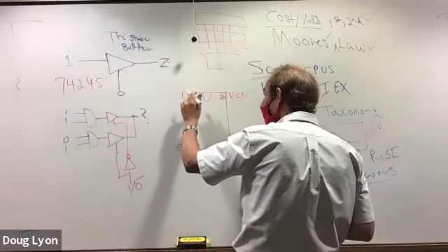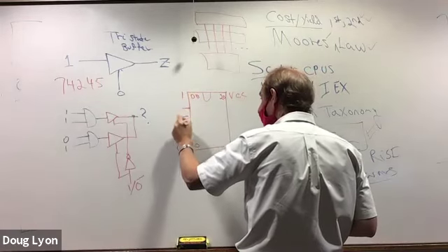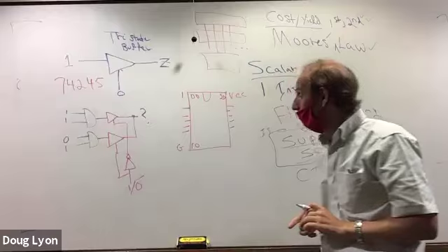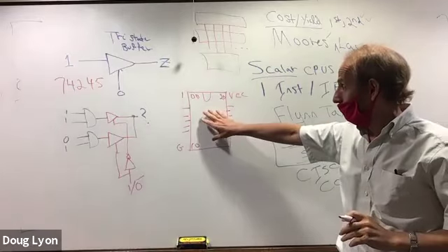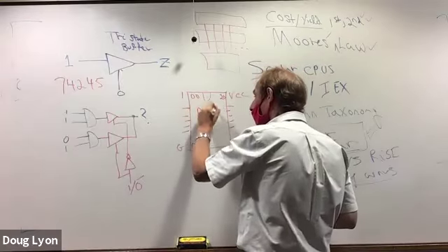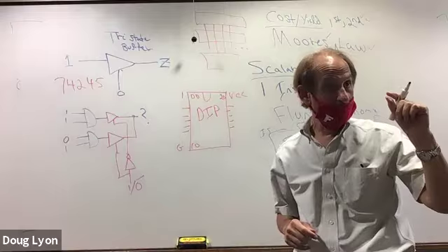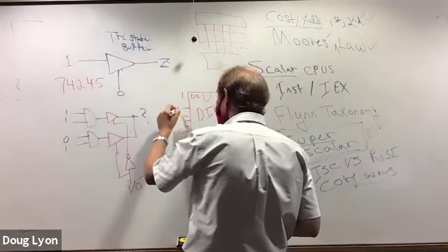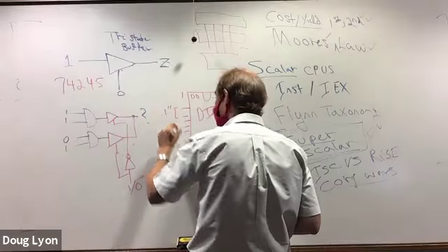And then stuff like this could be the data direction. And then you'd have pins for data going in and pins for data going out. When you take something like this as a DIP, this is a dual inline package, you will find that the spacing for the leads for your breadboard fit exactly because the standard is 0.1 inch.